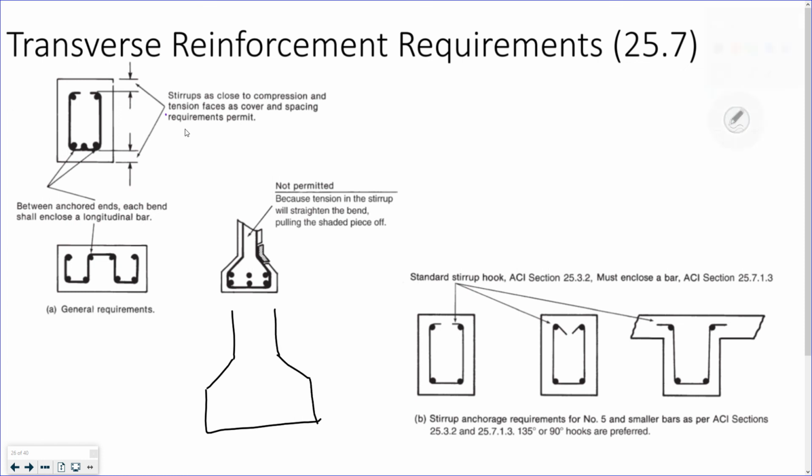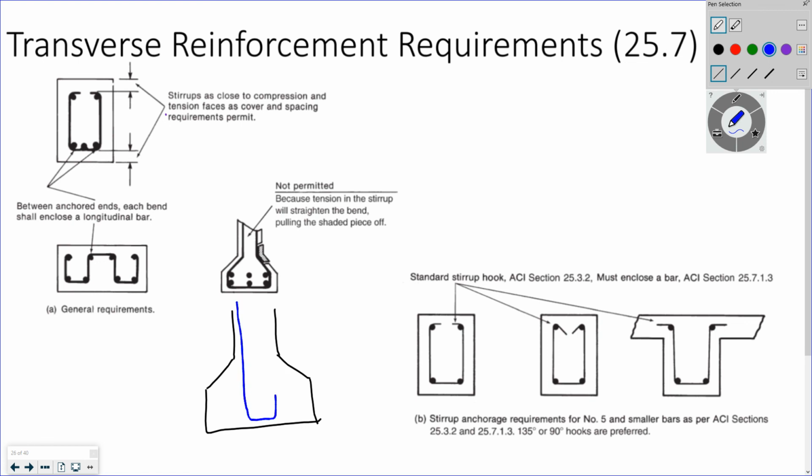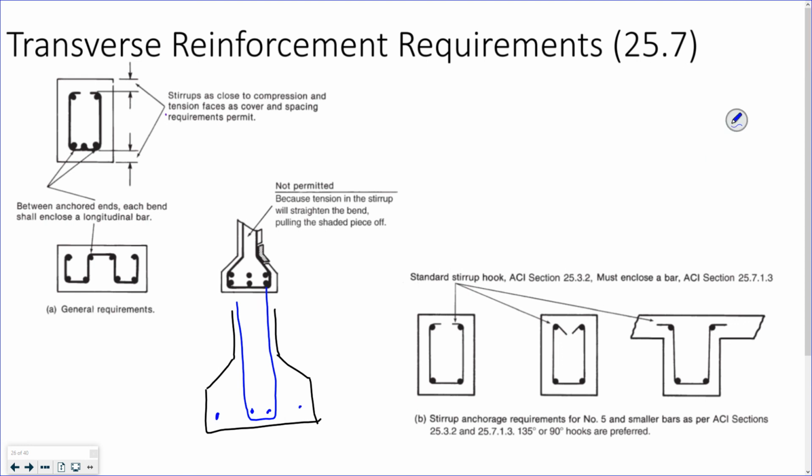So instead you would put reinforcement like that, not bend it like that. Again, you have to have a longitudinal bar helping it stay in place on the inside of that bend.